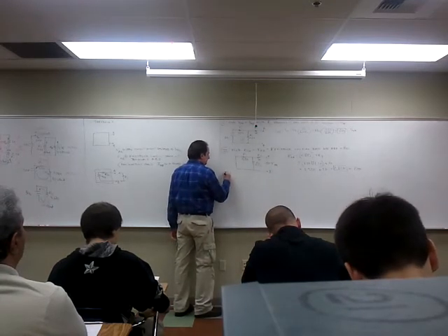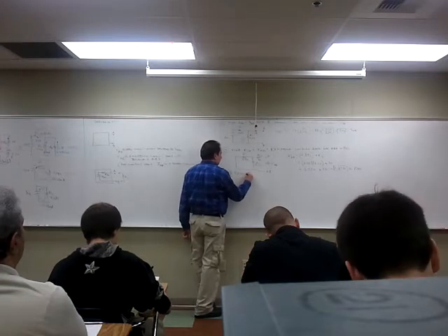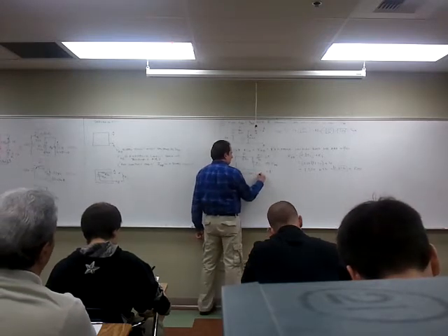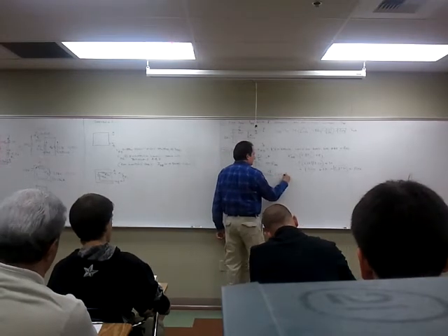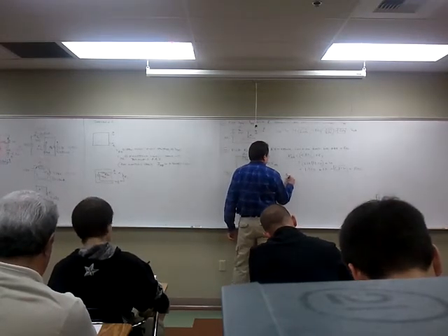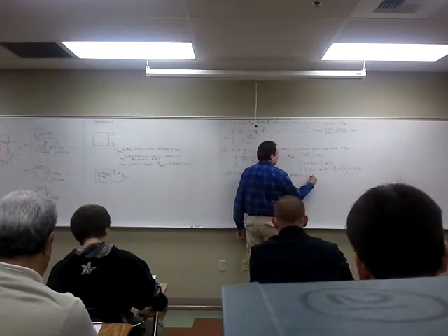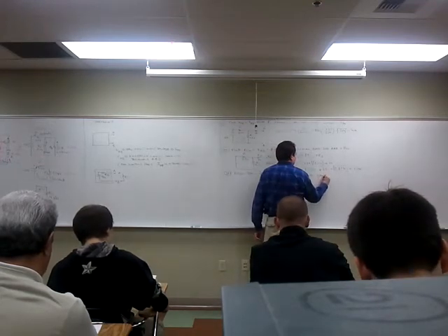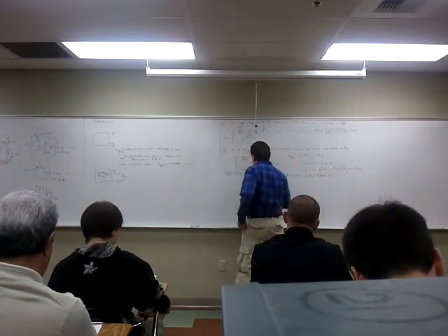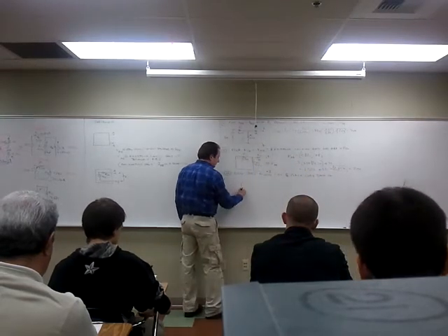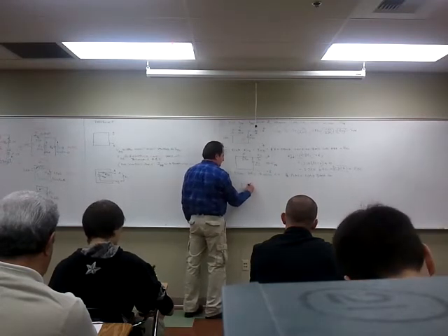Step 3. Draw the Thevenin equivalent circuit and place the load back on. So what is the Thevenin equivalent circuit? It is always a power source and series resistor.